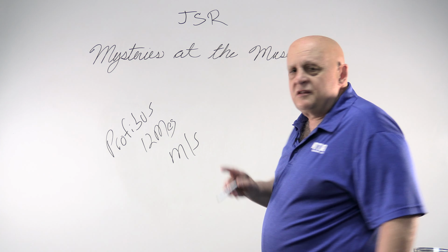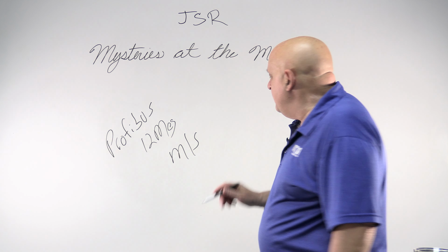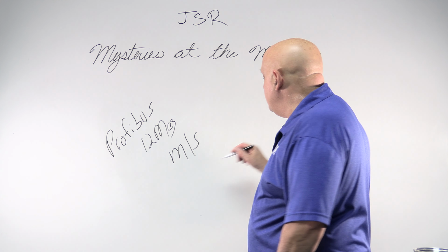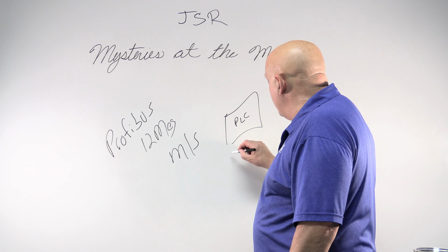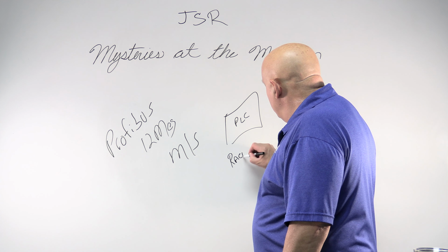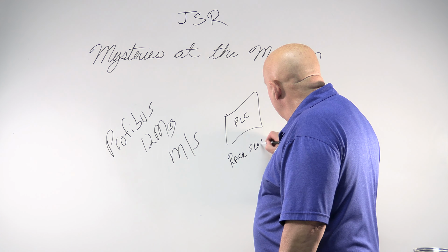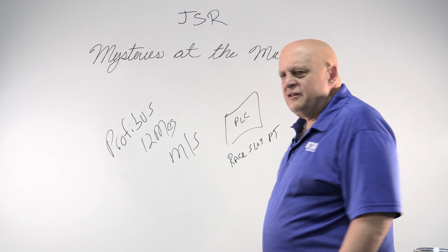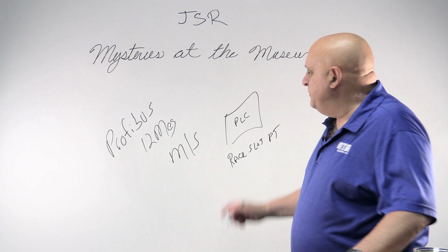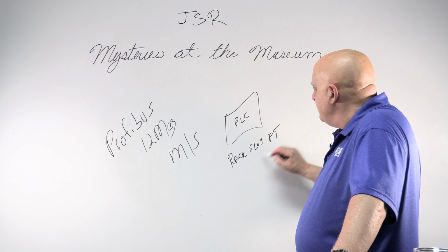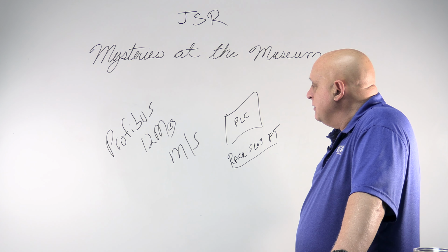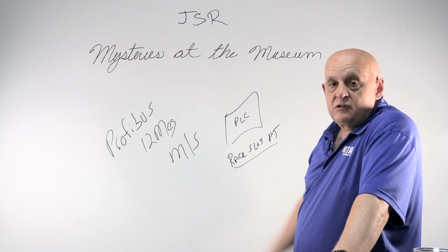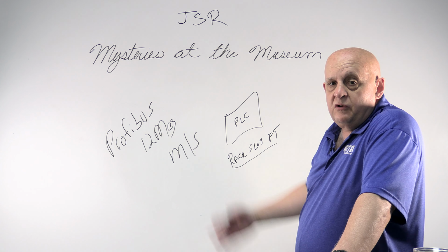The big problem with Profibus is the data representation: everything looks like a PLC. So you address things by rack, slot, and point. So it's a little bit awkward to make a device look like a PLC and fit into this rack, slot, point kind of architecture. But it worked well with Siemens PLCs. It was used all over Europe.